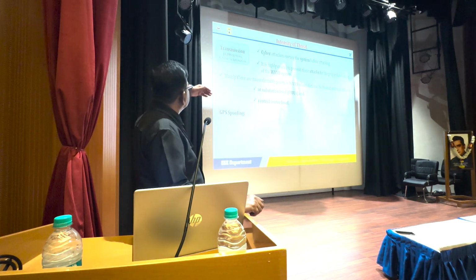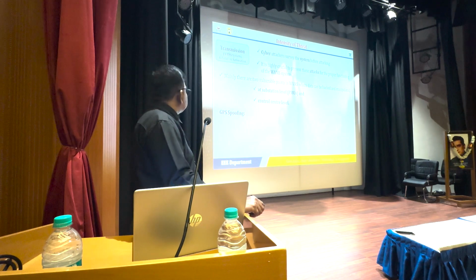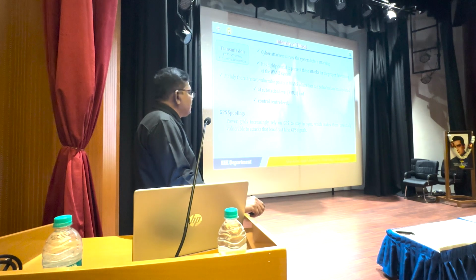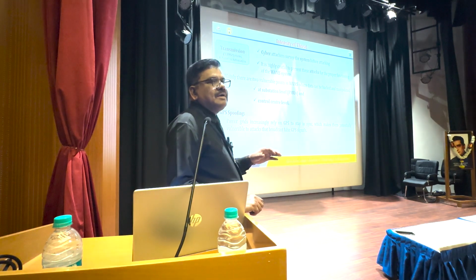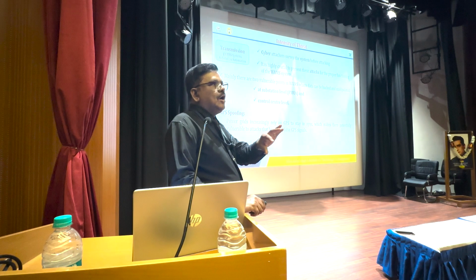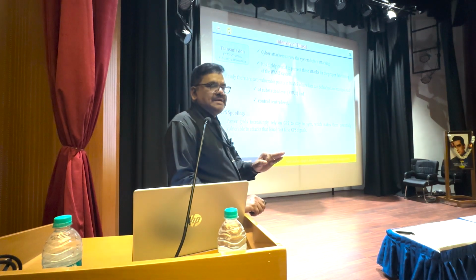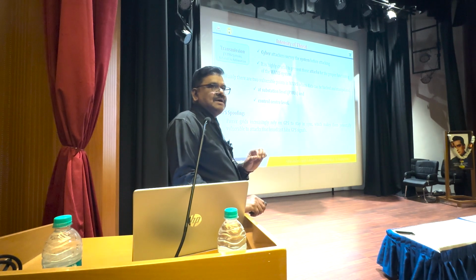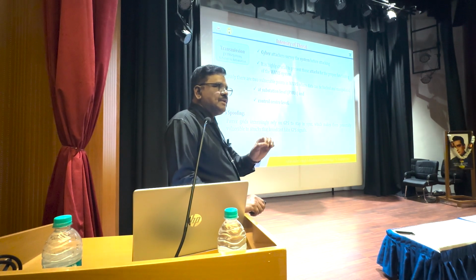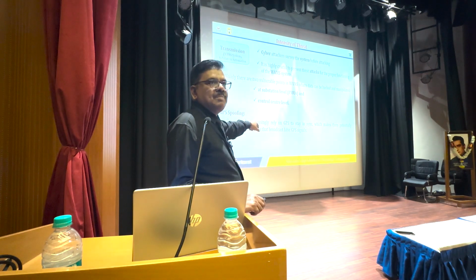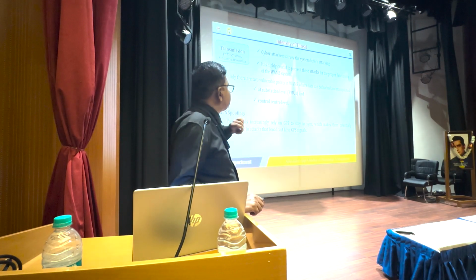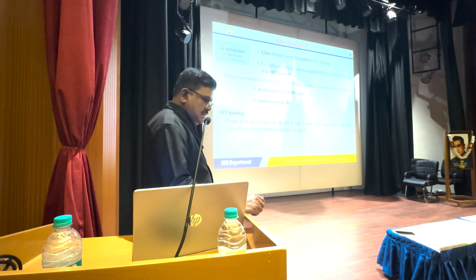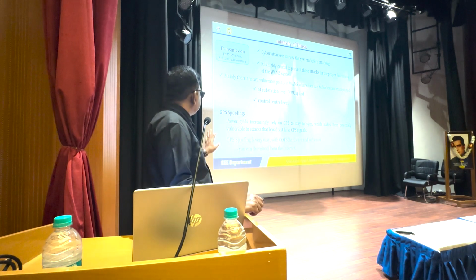These are the 2 vulnerable points the attacker can attack. So what is the type of cyber attack that has happened in the transmission system? That is GPS spoofing. The power system depends on your PMUs, and all PMUs are time synchronized. How are they time synchronized? To have a time 0 reference, they use the global positioning system. They use GPS to get the 0 time reference. Therefore PMUs are the target.